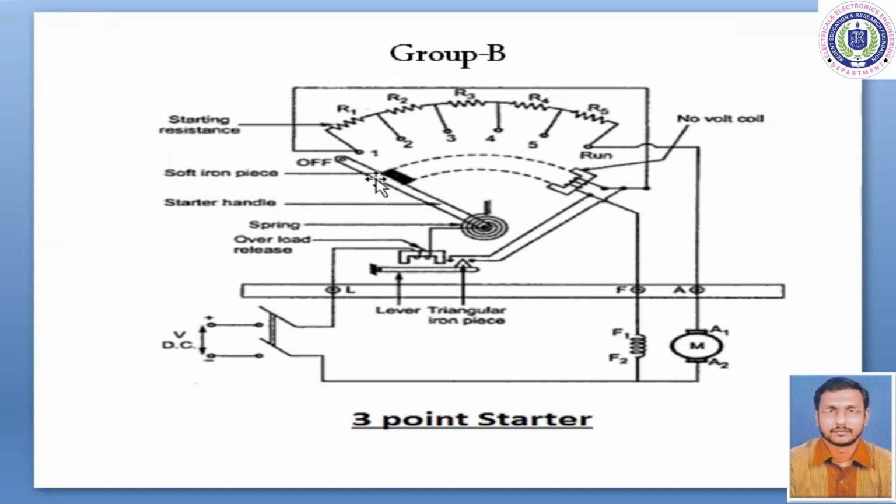That is the thing which you have to keep in mind. Again, as I have already mentioned, during the normal current passing through this overload coil, the overload coil will not be energized. But whenever the current is more than the rated current, the coil will be energized. And as you can see, below this coil, there is a lever. So whenever this coil is energized, it will push the lever in the upper direction. And at that time, the no voltage coil will be shorted.